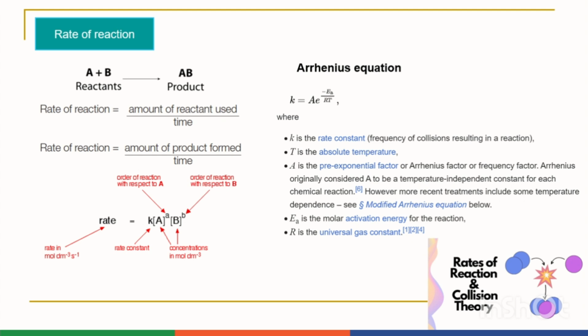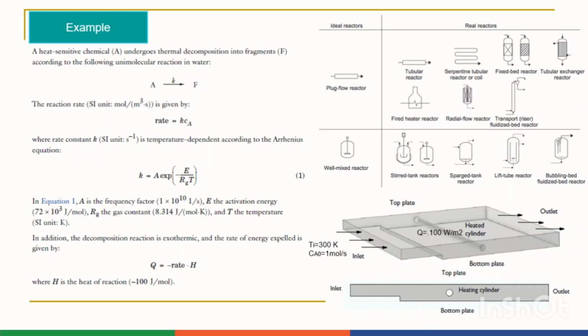Yes, now we can start to model an example for a chemical reaction in Comsol software. Today I'm going to study a plug flow reactor. So you can see here the geometry and all parameters which are needed for the simulation.